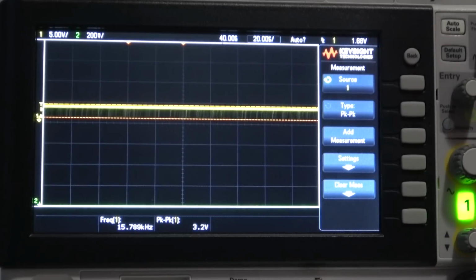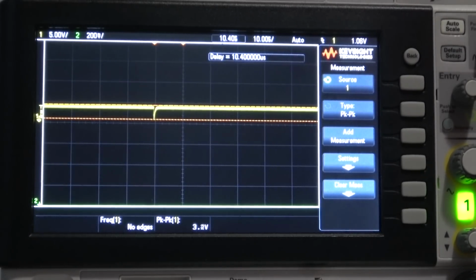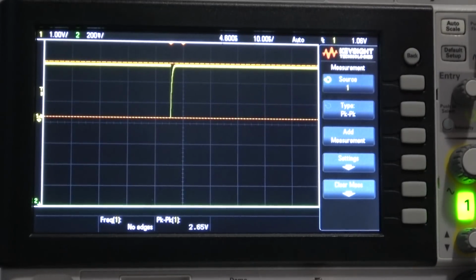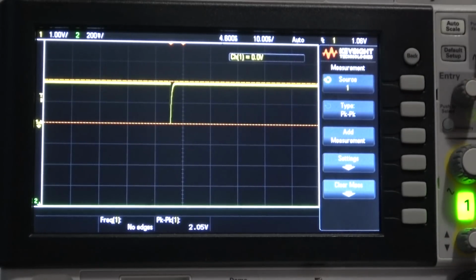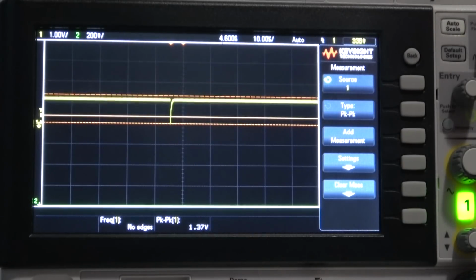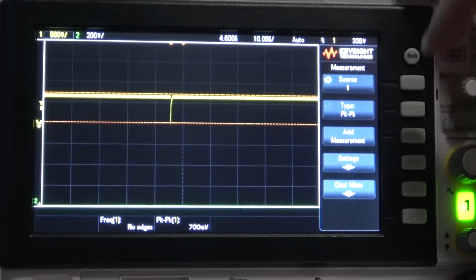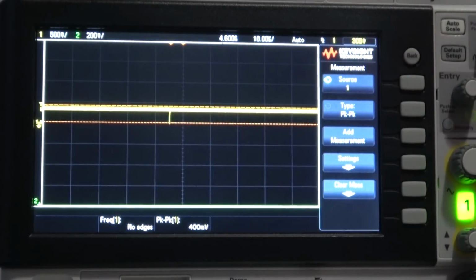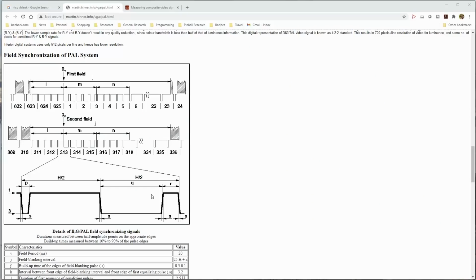Okay. All right, let's get our trigger. There we go. All right, let's zoom in on that. Okay, cool. We've basically inverted it. See that? I'm going to increase the division factor to 1 volt per division because that's what we need. Also, I don't think this is centered. Yeah, there we go. All right, so we're going to have the trigger pretty low. And let's zoom in even more. Actually, oh yeah, here we go, peak to peak, 750 millivolts. We want, oh man, that trigger's a hair trigger, isn't it? We want about 330.